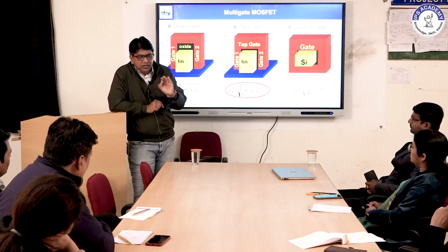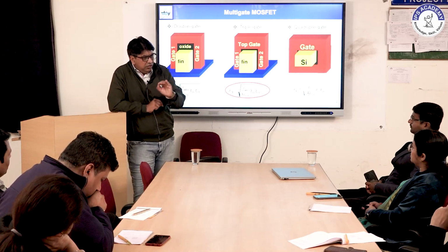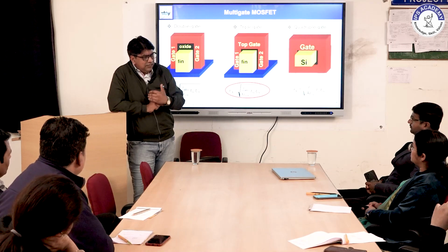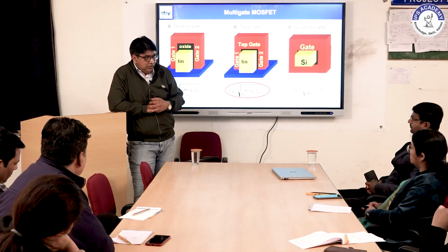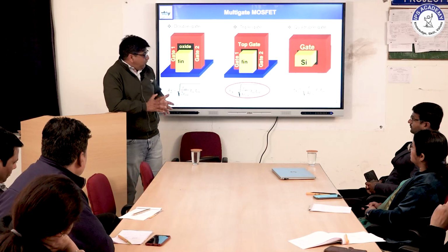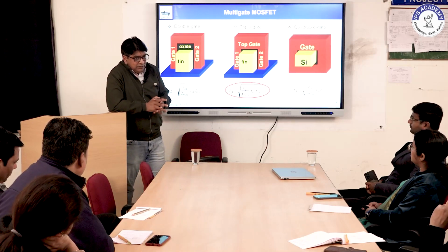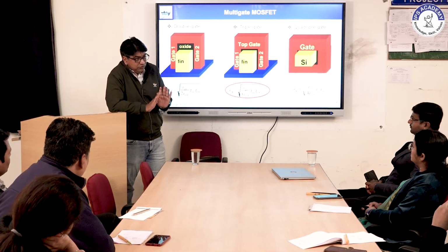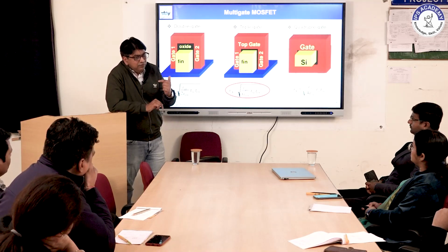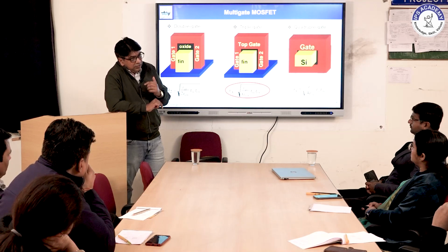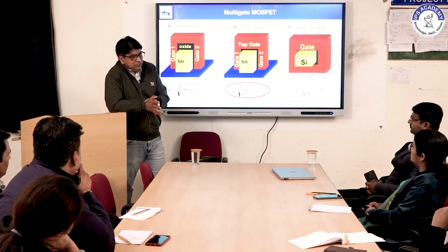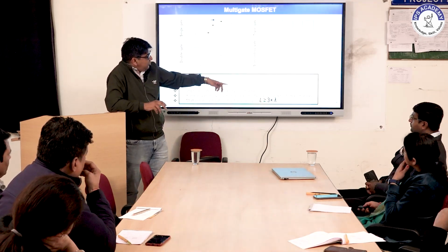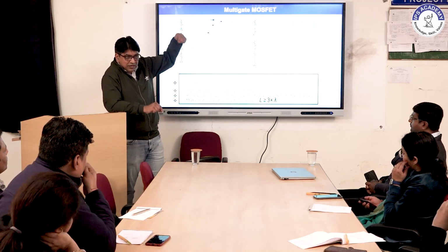It should become 60 millivolt per volt. Like that, if it is less than that, the device is a leaky device. Whenever we go for designing any device, the device will have some measurable values. If the measurable value is in our limiting range, then we can use the device for the circuit aspect.